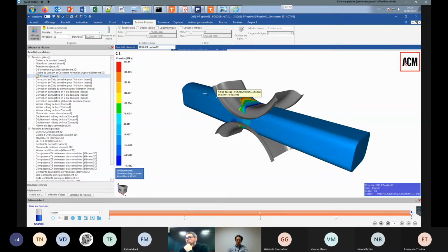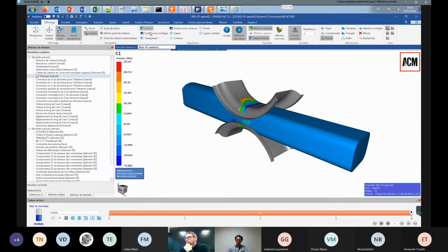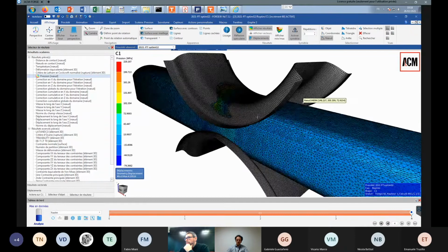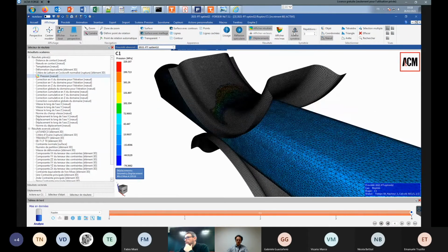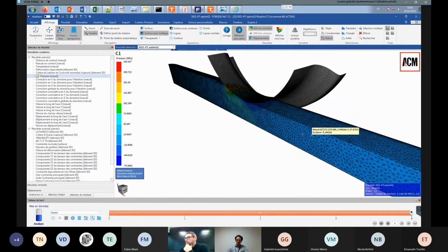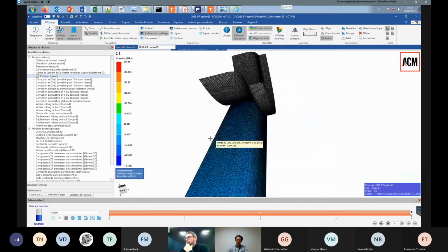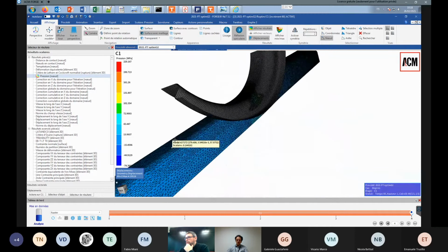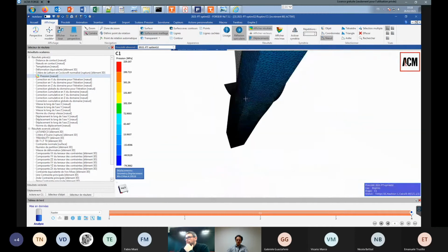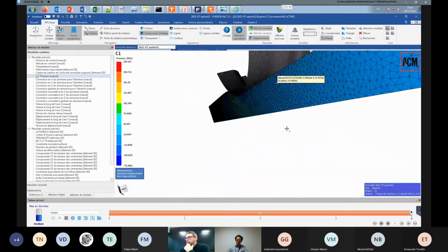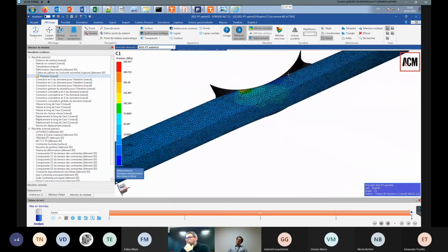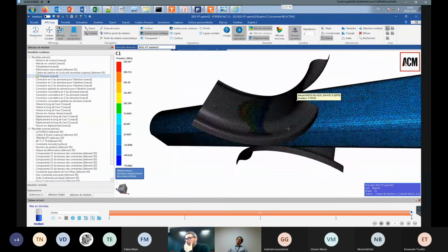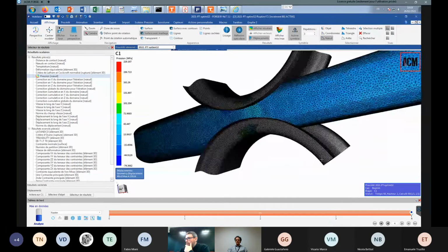Of course you can look at pressure and so on. If you see the mesh here of the problem, in fact, to be able to limit the time consumption of this simulation, we use a quarter of the geometry. We use symmetry planes, so we just compute on this part, and then we are able to see the whole results.